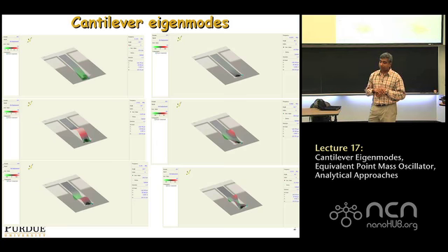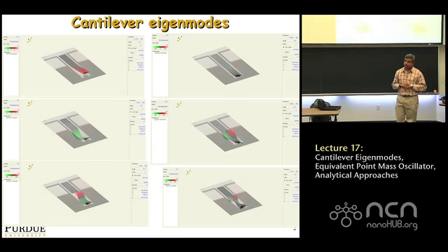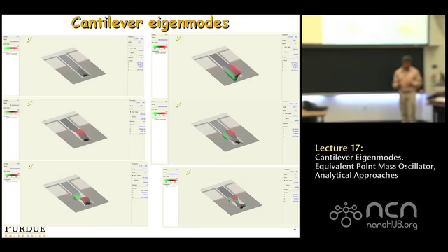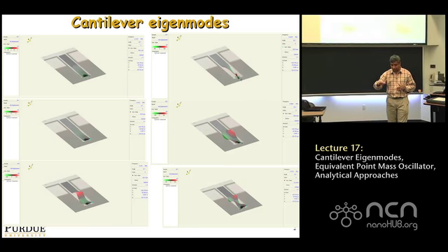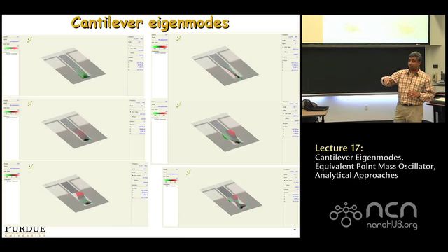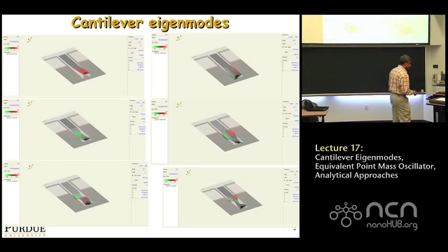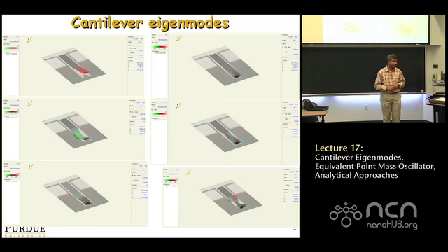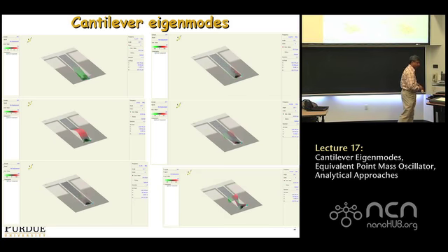And actually, if you look at it, there are many characteristic resonance peaks as you shake, right? Each corresponds to a particular motion of the cantilever. You can also get certain characteristic frequencies at which, when you drive it at those frequencies, it oscillates, it flaps back and forth like in a torsional mode, okay? This would be the first torsional mode. This would be the second torsional mode, which happens at even greater frequency, and then you get the third torsional mode, which is at really high frequency.